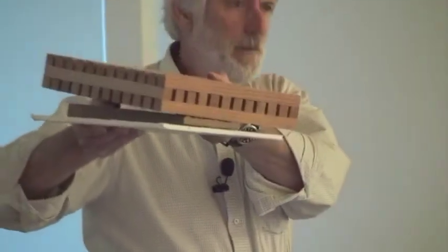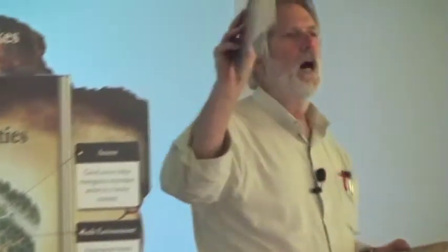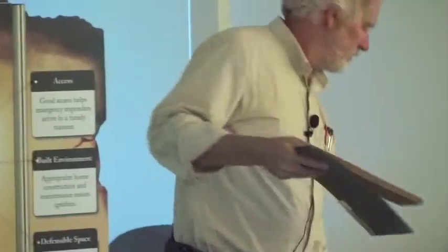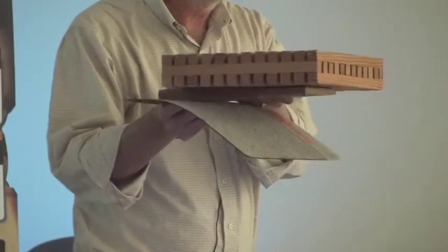This is something called Densdeck. It's a gypsum fiberglass product. When you have the assembly like this, you can put the Class A on top of it, and it'll pass the test. Similarly, you can put this roll roofing on, and it'll also pass the test. So you're good. You can go either way.